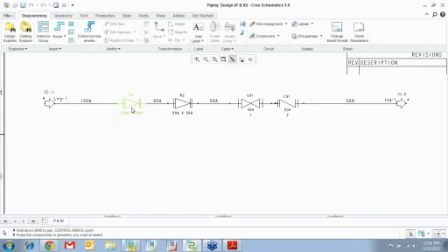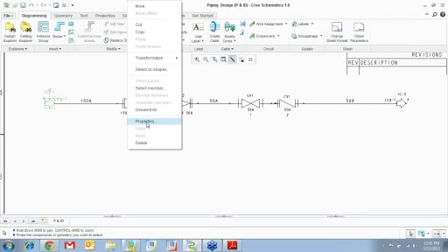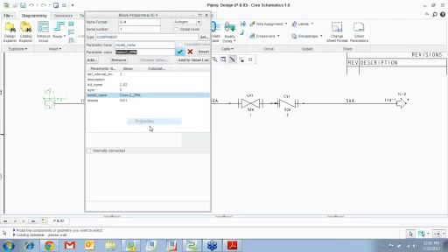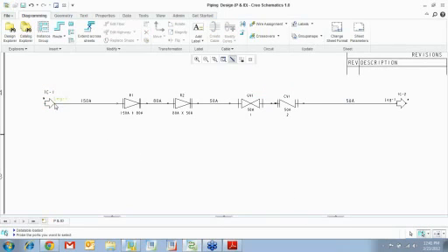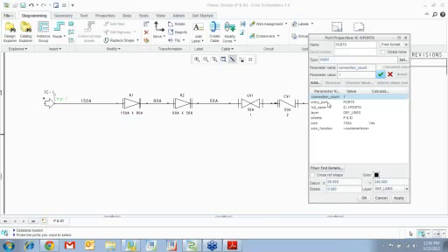You see they have a reducer, they have another reducer, they have a gate valve, they have a check valve, and all these. Okay. Even here, if you select a particular symbol, you go to its properties, you see that its model name is that. If you also go to its port and pick the properties, you see it's using port 0 coordinate system.